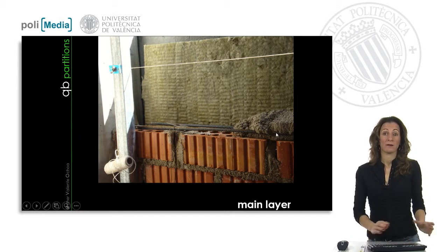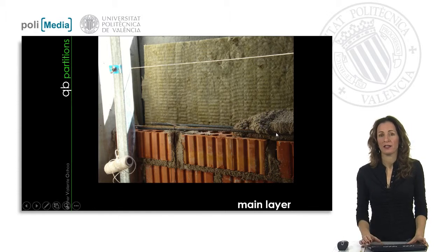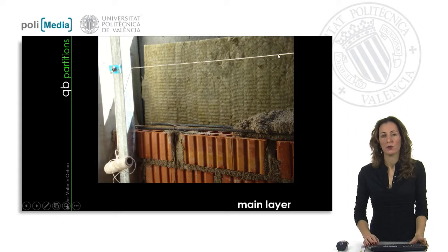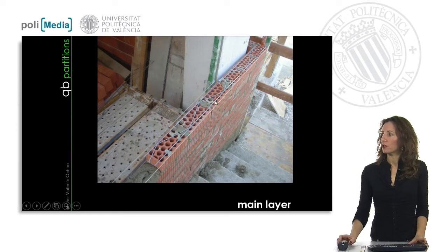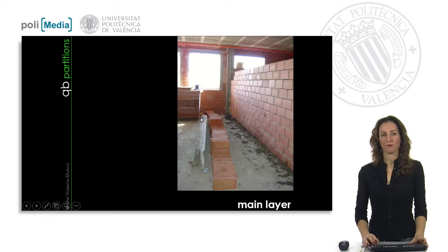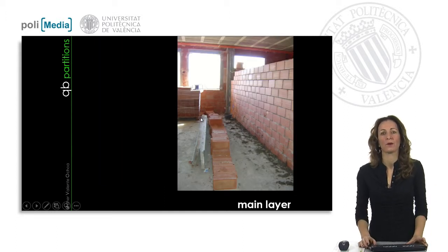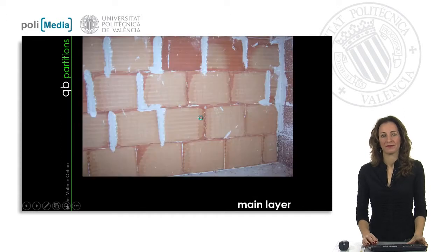Depending on whether the main layer is covering a secondary one or is covering just the finish, we also have to check about the possible insulation between both lines. During the main layer, we can also use a thinner reinforcement like this one and just run the whole construction of our brick wall, row by row, following the position of our rope, building it up.